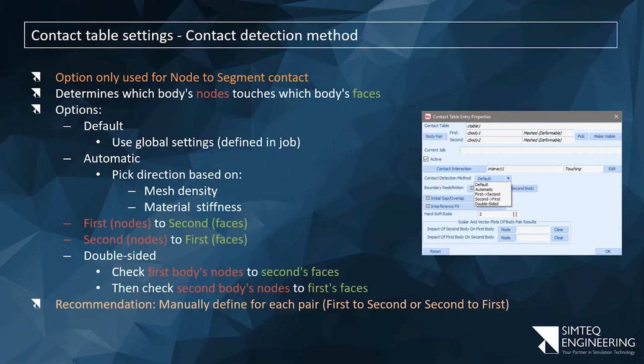And one of the reasons for that is sometimes you get to this point and you realize, okay, but I've got both fine mesh, but also the lower stiffness on the other part. And that shouldn't work. So then you can immediately go back and try and fix that. But still, by doing this, you can ensure that what you expect the model to do actually happens. So I just have a lot less issues if I manually define all of these.